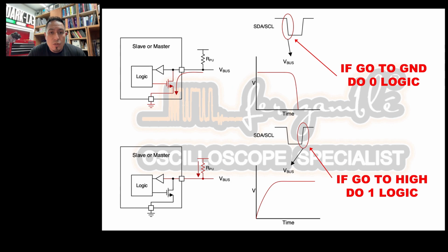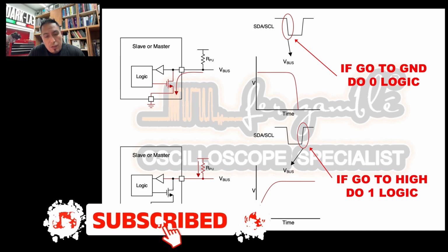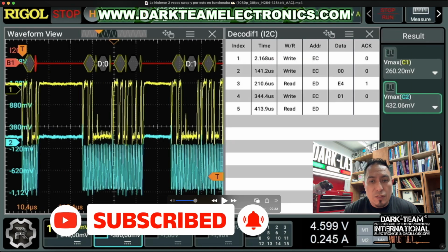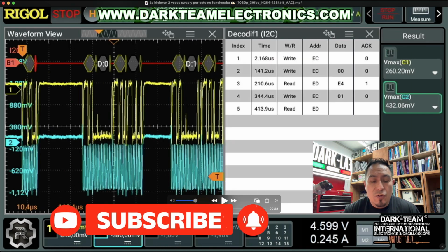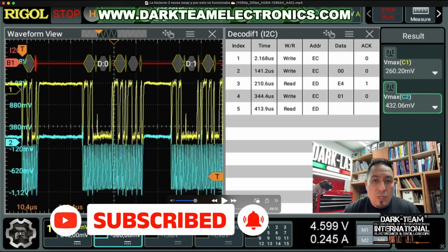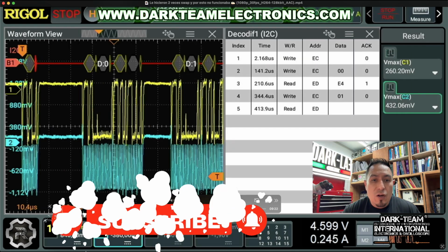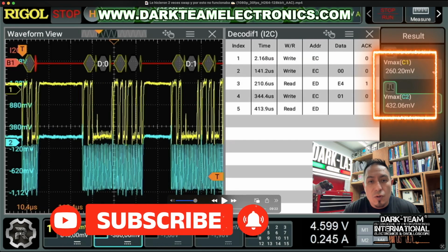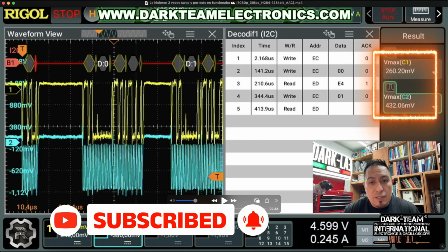How does this work? The logic block controls the MOSFET, and the MOSFET is responsible for making the state change, whether 0 or 1. And now we know that the voltage the pull-up resistor has at the input comes from the PMU, and that the MOSFET is controlled by voltage. Then, if our problem is a low voltage level, this is not a problem of the PMU or the resistor. Rather, it is a problem caused by a leak in the line.